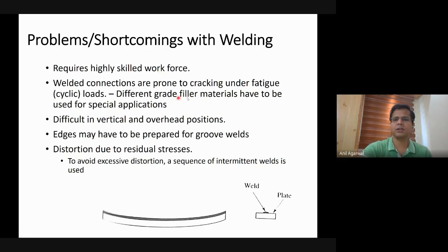Usually the one that we go with does not have a very high level of ductility. Therefore, wherever you have a requirement of a high level of ductility, or you have to operate under very low temperatures, or you are expecting impact loading, in such cases it is better to go for a higher grade filler material. When I say higher grade, it is higher grade from the ductility point of view. Okay.